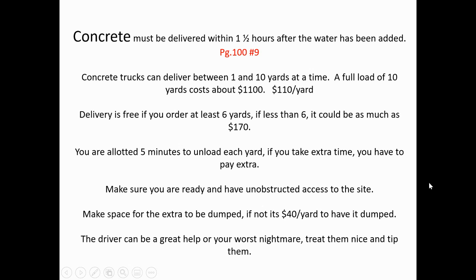All right. So when you're getting concrete delivered, it must be delivered within an hour and a half after they put the water in. Right? Not that big of a deal, you think. But what happens if you are building a skyscraper in New York City? There's not a lot of concrete plants in downtown Manhattan, so the concrete truck might have to come from New Jersey. It might get stuck on the bridge in traffic. So you really only have not that long a time to pour that concrete.